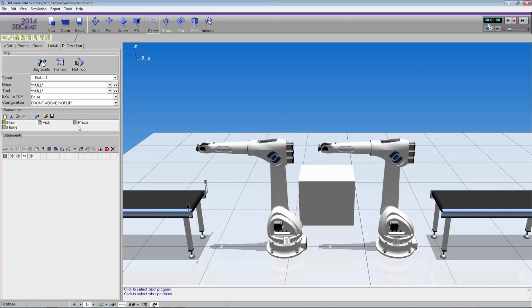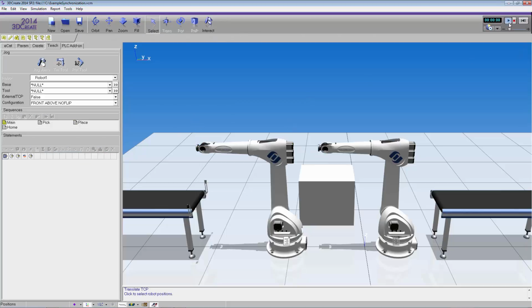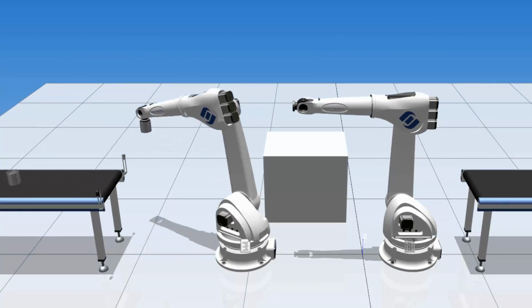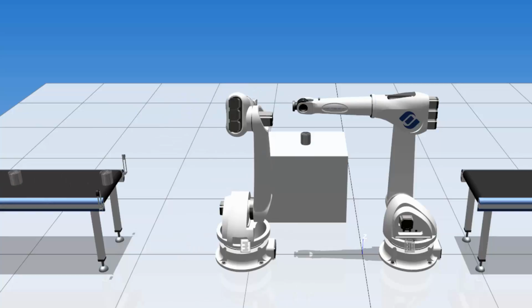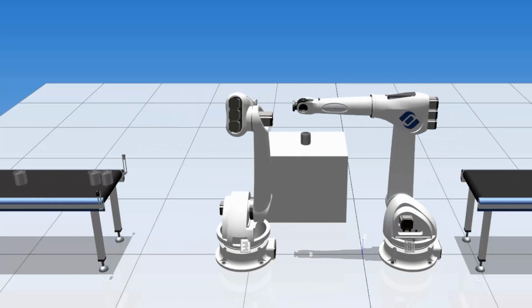And for Robot 1, after it does the pick or the place routine, let's go and add another position. So we'll just move it out of the way just a bit over here. Make that a point-to-point motion statement. Move it to the end of the place subroutine. So now if we run the simulation again, we should see the final result. Hopefully it looks good. All right. Robot 1 picks and places, waits, Robot 2 picks and places, and then they move together.